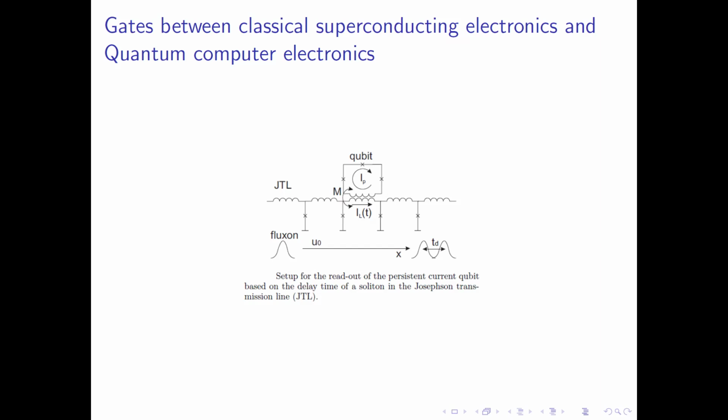The problem is that usually this rapid single quantum flux electronics can work, depending on the material, in NbN and Nb, like niobium, at 10 Kelvin, let's say. Then it is a relatively high temperature, but it can also work at lower temperatures. There's no problem with that. The problem is that writing of a superconducting qubit by means of classical information representation by vortex always leads to heating up of the qubit. So this communication process is going to heat up the qubit, so it cannot be done too often.